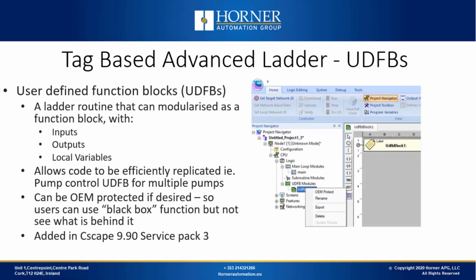UDFBs can also be OEM protected, meaning you can, if given permission, use UDFBs that were created by others through a black box. These UDFBs would otherwise be unavailable to you as they contain valuable logic or code that the creator does not want to share. This is created so that you can still use these UDFBs, but not be able to replicate the logic or code behind them. It is important to mention that support for UDFBs has not been available until the release of Cscape 9.9 Service Pack 3.